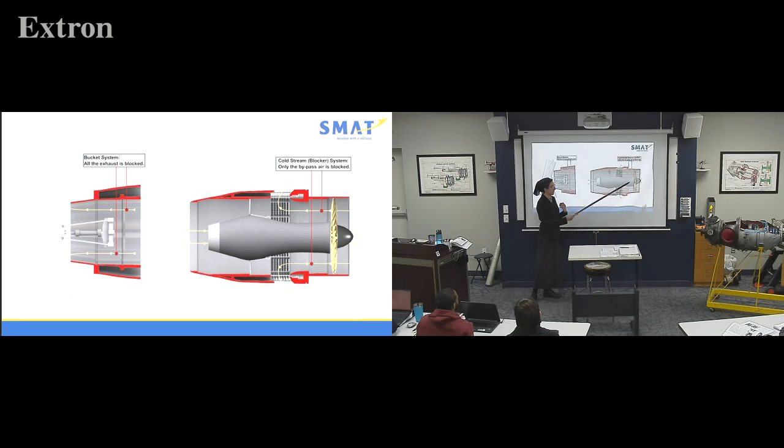These are on turbofans, so just our fan air is blocked internally. These would normally be closed in flight, but when you deploy thrust reverser, this slides open, and vanes come down and block all around the engine, blocking the fan airflow to allow the air to come out the side.